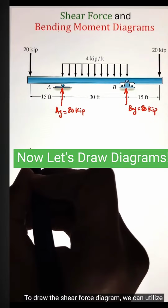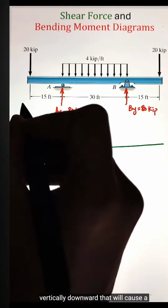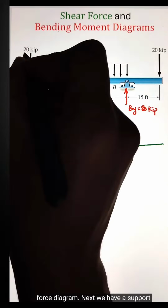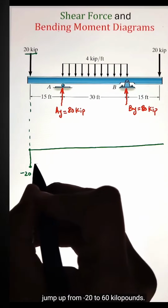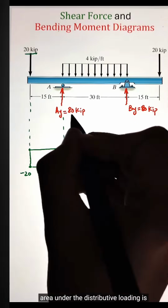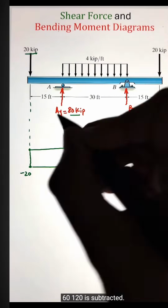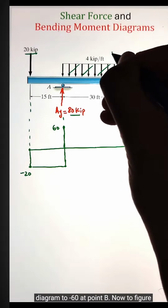To draw the shear force diagram, we can utilize the loads acting on the beam. To start, we have a 20 kilopound load acting vertically downward that will cause a jump down from 0 to negative 20 on the shear force diagram. Next, we have a support reaction of 80 kilopounds that will cause a jump up from negative 20 to 60 kilopounds. After that, we have a distributed loading acting vertically downward. The area under the distributed loading is coming around 120, meaning that from 60, 120 is subtracted. That makes our value on the shear force diagram negative 60 at point B.